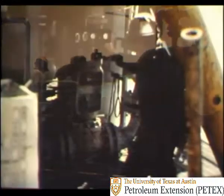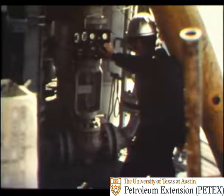The next external feature is the back pressure control loop. Without such a means to hold the right pressure, the separator and other equipment downstream of it will be in a constant upset condition. This would cause improper separation, carryover of liquids with the gas, and other undesired effects.